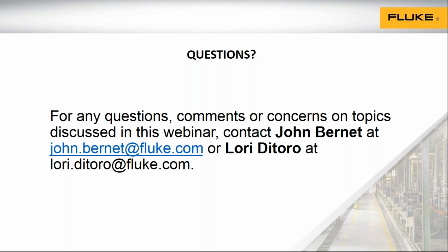This one's pretty specific. Are there any condition monitoring tools appropriate for pneumatic and hydraulic cylinders? Oh, that's a great question. As a matter of fact, 3 or 4 years ago, we had a hydraulic study, and what we found was that several of our tools will overlap and support the hydraulic industry. For example, if you think about the hydraulic pump and the motors and the rotating components that are part of the hydraulics, vibration and motor testing are all going to be applicable.